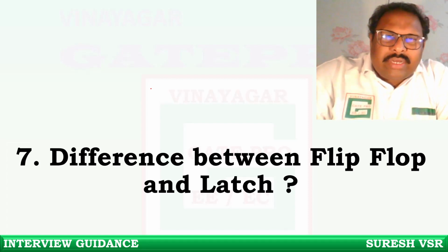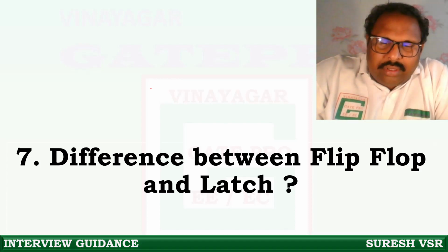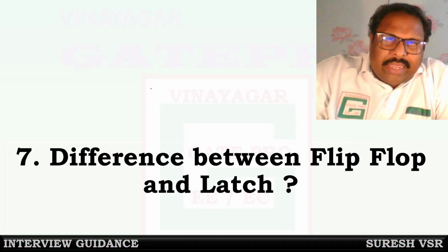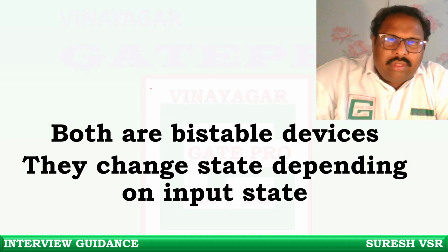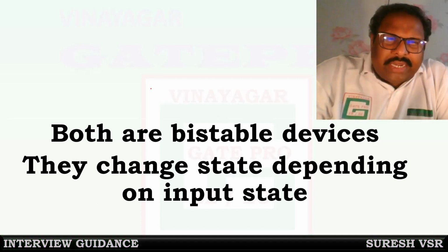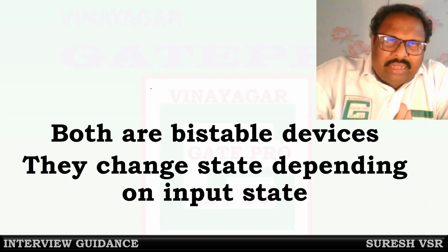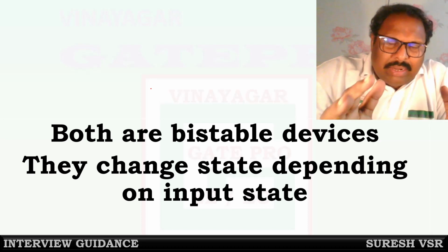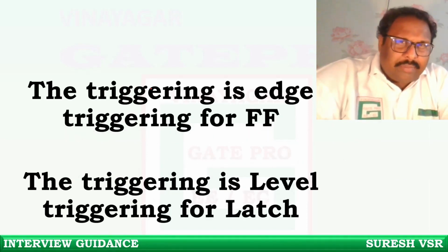What is the difference between a flip-flop and a latch? Something interesting: a flip-flop and a latch are almost identical. Both have binary states, set and reset, or 1 and 0. They both change their state depending on the input. They both have two stable states; both are bistable devices. The major difference is in the triggering.